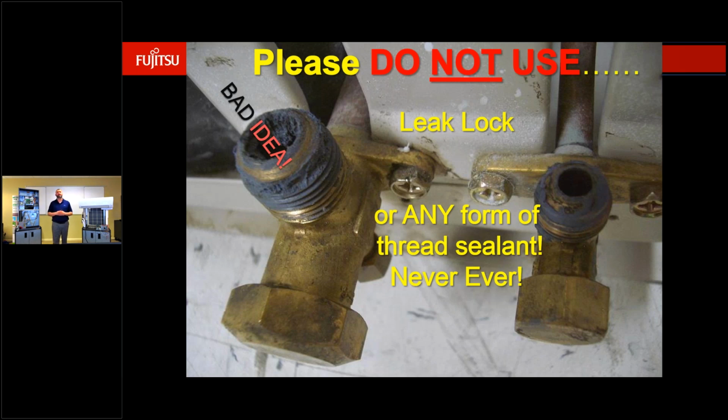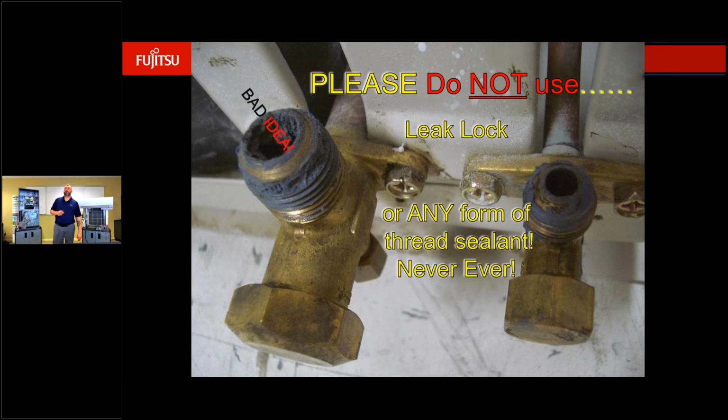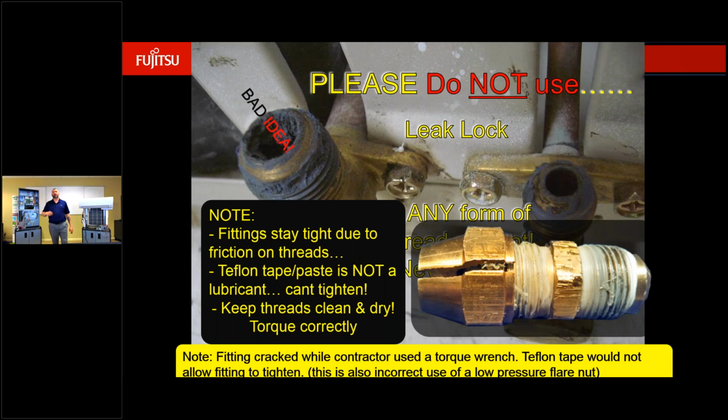It's not something that's necessary. They are very precise when they do these fittings, so we're not looking to add anything to the surface of that. Bad idea. What happens when you use these things? You could have a flare nut end up snapping on you, and then obviously that's going to lead to some installation issues at that point.